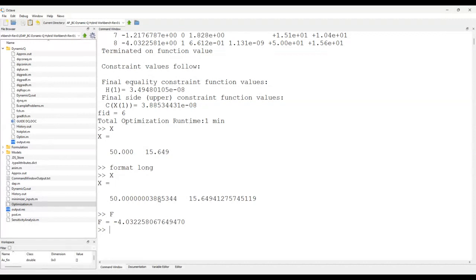Another example, if I'm now talking about my own project as well, would be changing the design variables based on the geometry of the Stewart platform. So you might want to change the distance between two legs, but you also want to maximize the acceleration that your platform is going to achieve. So you want to minimize your actuated forces, but you also want to maximize the acceleration. That's an example of a multi-objective optimization, something like a Pareto optimization.